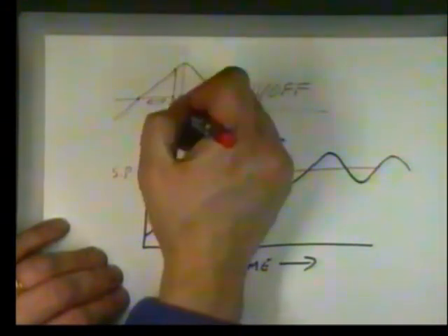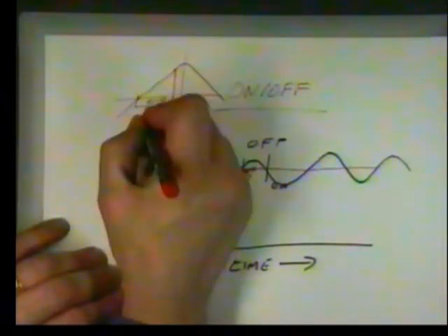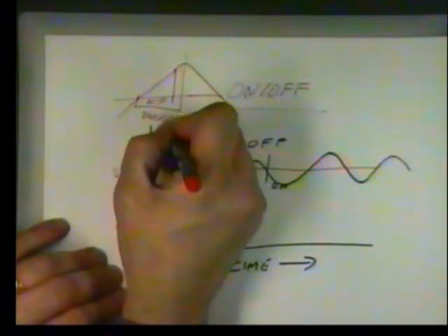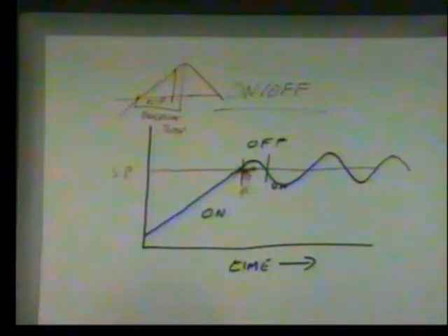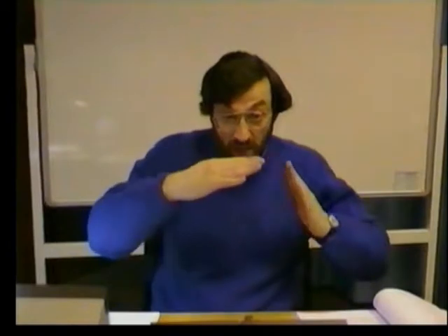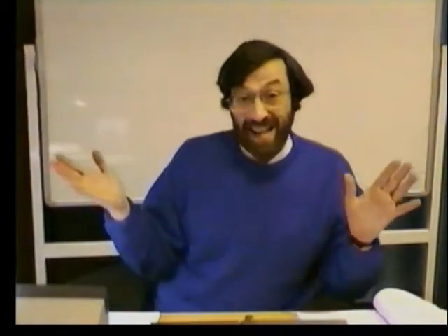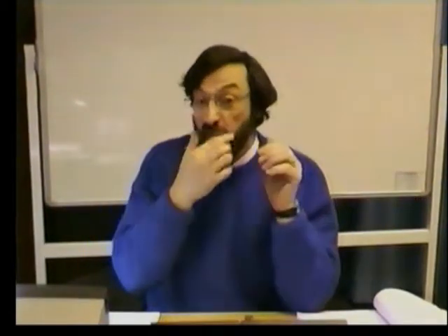Because these are real events in real time. So there is always the processing time taken from the point where the real events occurred. We've crossed our set point. It's only some time later. It might only be milliseconds, but it can never be instantaneous. It always happens some other time.